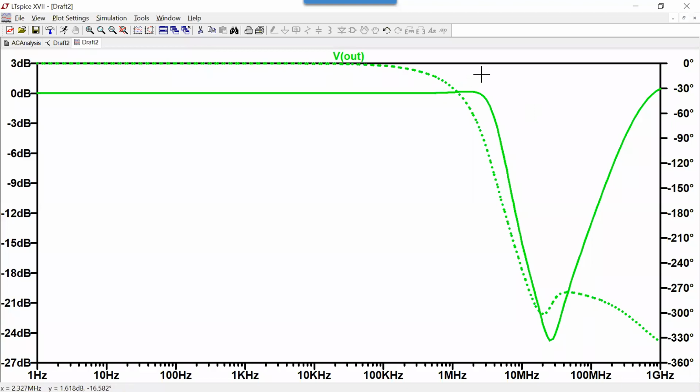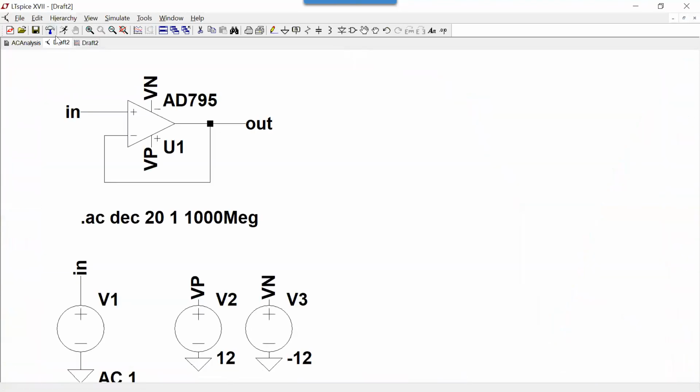that feedback network is actually causing a peak here, which means there's a complex pole. Then it comes down, and it's coming back up. So that's kind of pretty wild. It's not working there, right? So all you would have to do is circle where it's kind of deviating, right? Now, there's other things as well.